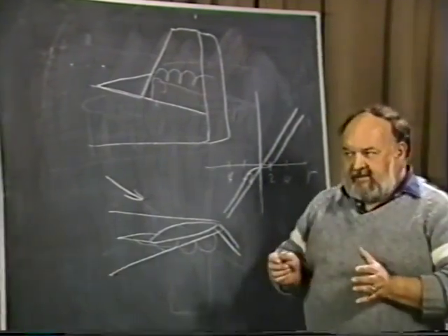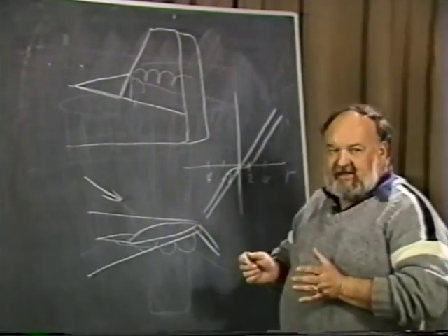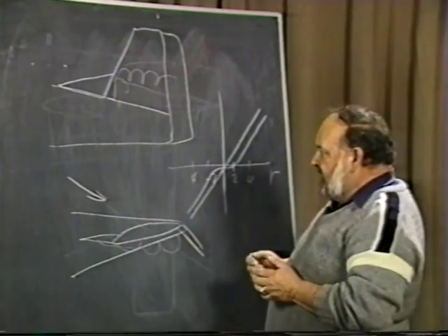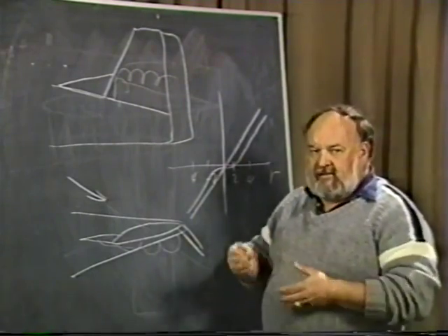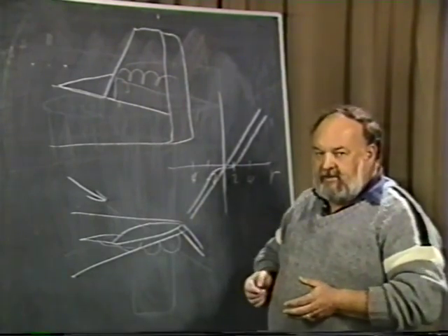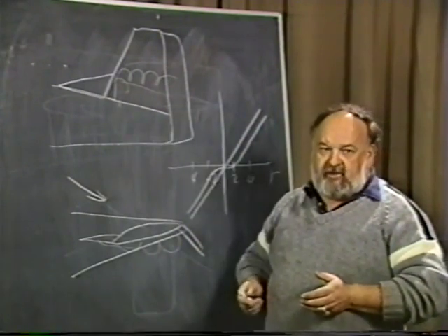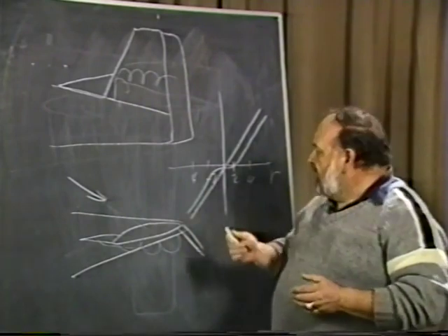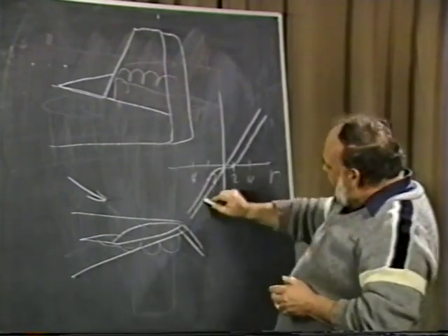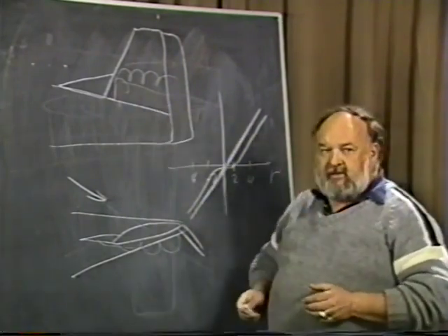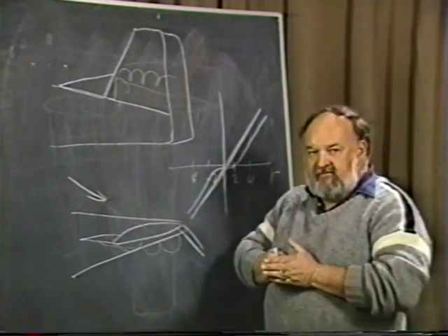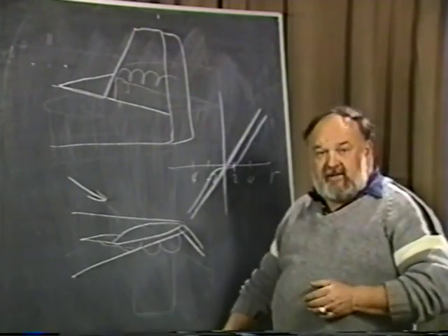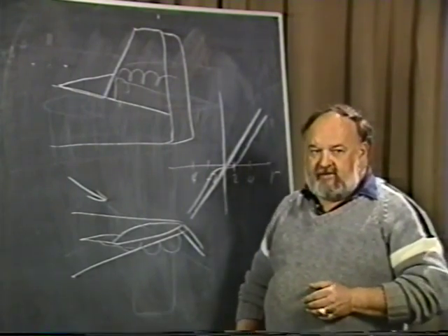When you have an airplane that sits there and it's loose in directional stability, that's the way the pilot would feel, and then it starts to get heavy as you start to apply controls into it. You got this unbalanced, uneven forces. A dorsal fin is a very strong and powerful thing to do that. On a Yankee, that's exactly what we did. You put a little dorsal fin up on top, and it brought this curve out to be almost a linear condition from zero angle of yaw, right or left, either way, on up through. And that made the flying qualities, the handling qualities, very, very nice on it.